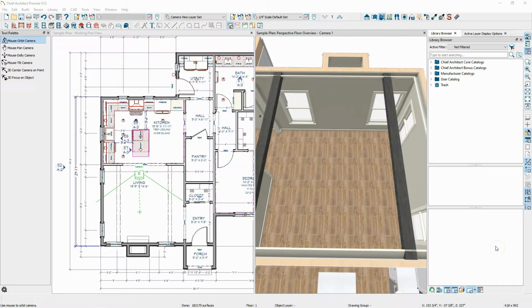As you remember, when we built the exterior walls of our house, we have this chimney area here that we just built out, but we didn't do anything with yet. So now we're going to add the fireplace. The way that I like to build the fireplace, and what I find is the easiest way to visualize it, is to use a window feature.